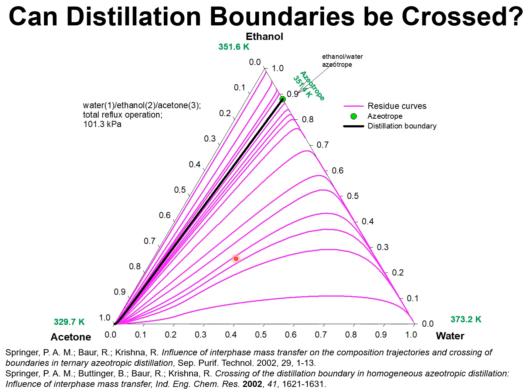Put another way, if we follow the concept of theoretical stages and residue curve maps, a distillation column with feed mixture anywhere here cannot be distilled to produce pure ethanol. That is only possible if we have feed mixtures with compositions on the left of the distillation boundary.